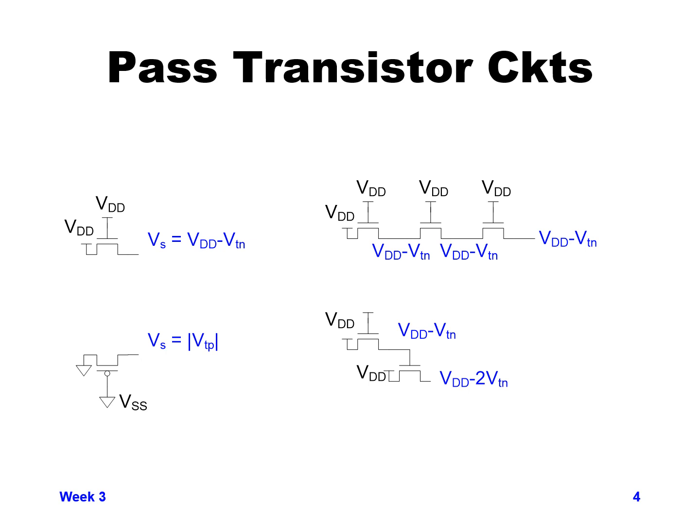So in this case, the output of the first one is the same as we've been looking at, VDD minus VT. The output of the second one has to be 1 threshold voltage below the gate of its transistor. Since that gate transistor is at VDD minus VT, 1 threshold voltage below that is VDD minus 2 VT.